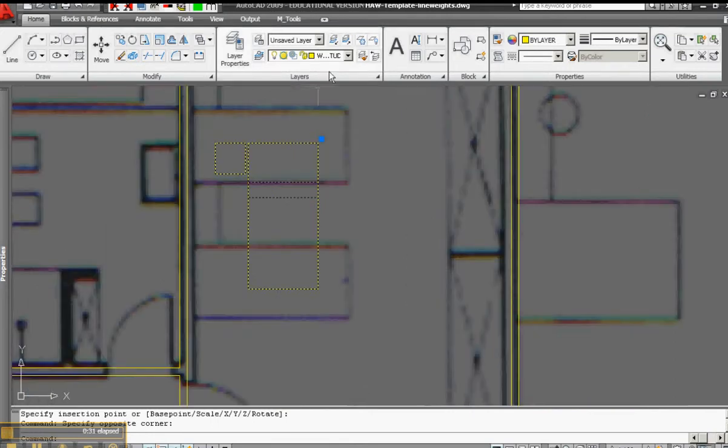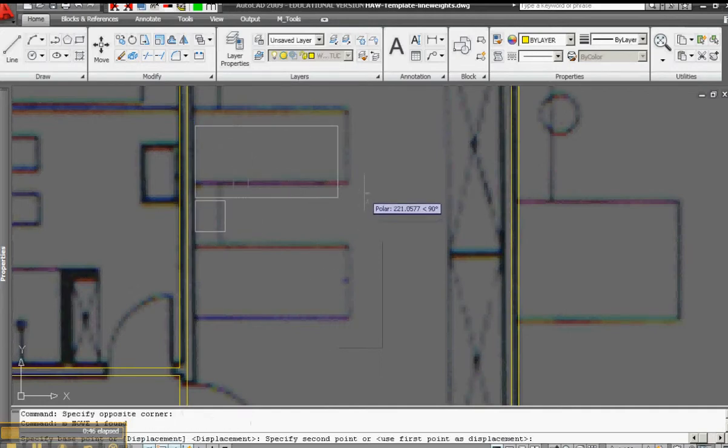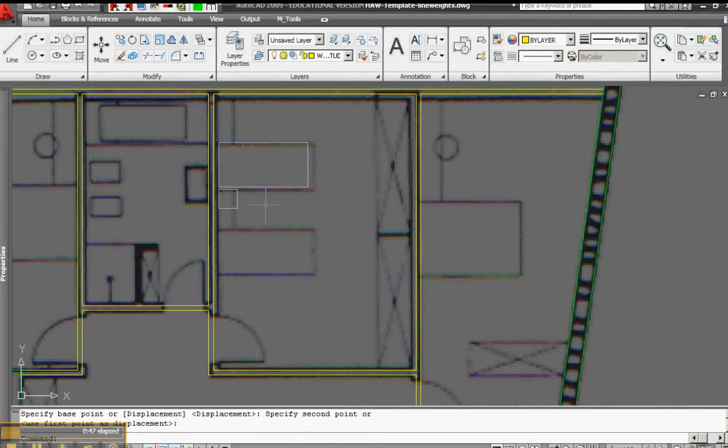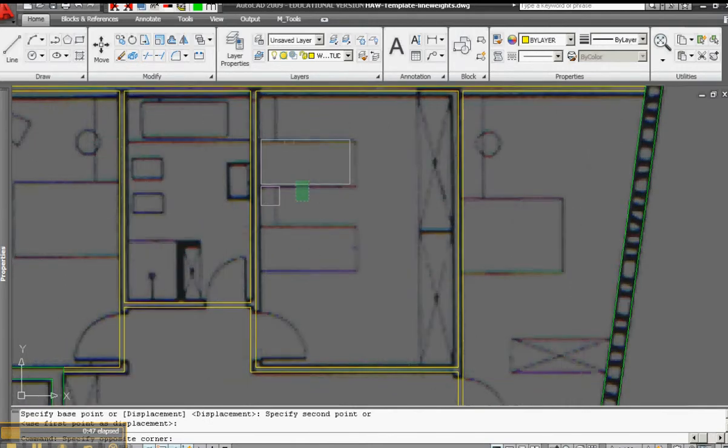It's good to move that onto a furniture layer, or whatever layer your block sort of is. Rotate 90 degrees. And because the block was drawn on layer 0, it will inherit the layer qualities of whatever your current layer is, or whatever you put the layer onto.